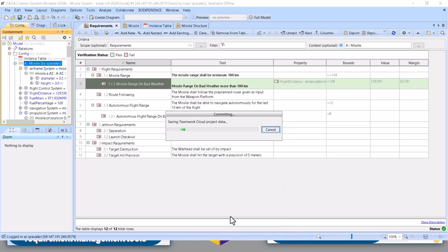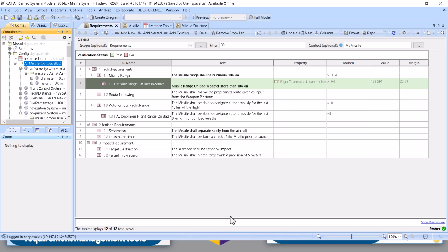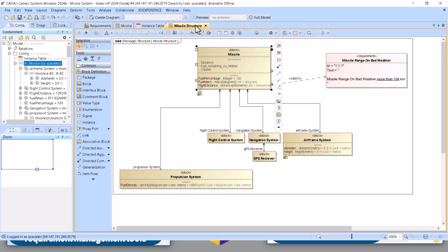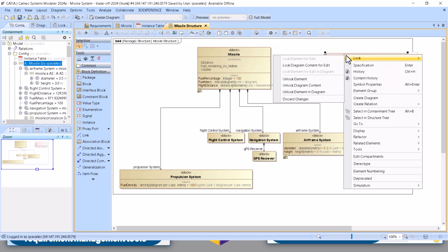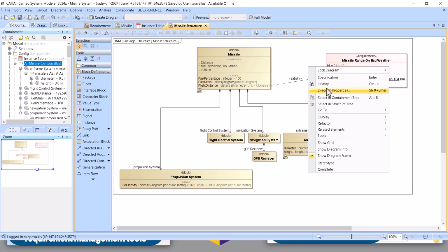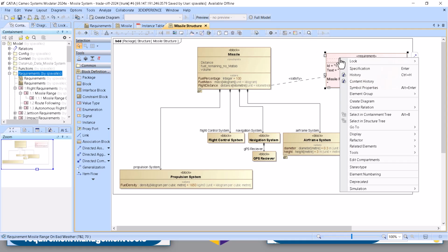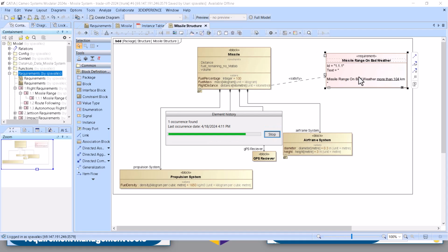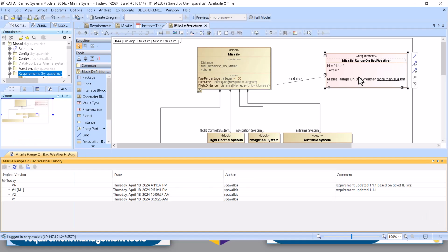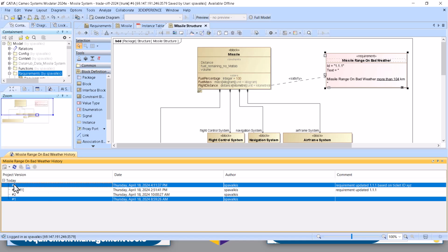Now once the changes are committed, you will always have them in the repository. There is no way to delete that historical commit, and all those changes are tracked at the single element level. So if I want to see how this changed, I can right click and say history for element, whole diagram, package as a scope, and whole project. So I can go here, right click, history, and that's because it is a database. It extracts the changes and shows me what the changes are, at which version, who did them, and which command changed this specific element. They can compare, you see, between the last and the recent one, and do a quick diff.